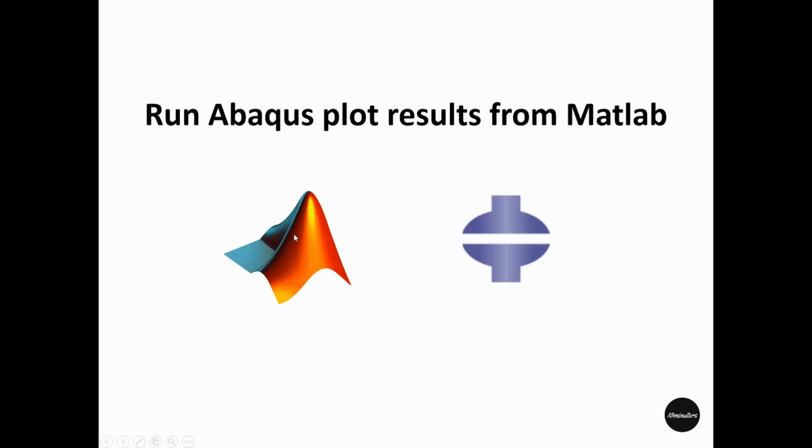Today you will learn how you can use Matlab to run an Abaqus job and extract quantities like force, displacement, etc. at a node or at a reference point. Also quantities like stress, strain at elements. You can do all of this directly from Matlab using the simple steps I am going to show you now.